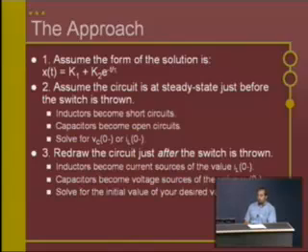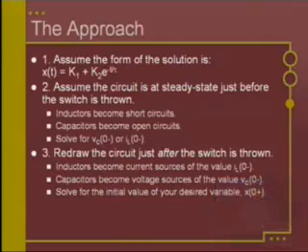And then, depending on the type of storage element that happens to be in our circuit, we're either going to solve for the voltage across the capacitor, which is going to be a similar kind of solution to the open circuit voltage in Thevenin analysis, or we're going to solve for the current going through the inductor, which will be somewhat similar to the short circuit current of a Norton analysis.